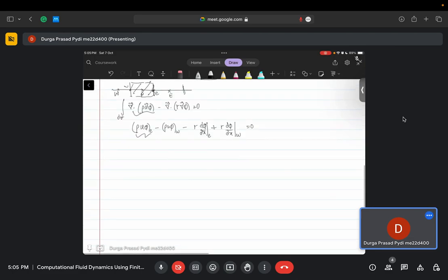In this particular term, u and phi, if the velocity field is known, that is the problem we were solving last week. If the velocity field is already known to us, then rho u is essentially the mass flux that we already know of. The delta x term is eliminated. So the problem that remains is to determine the value of phi east. Phi east is the value of phi on the face centroid. So this is a function of both, there will be a component from the diffusion.